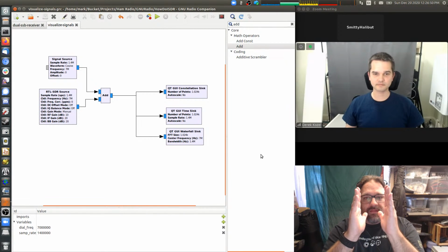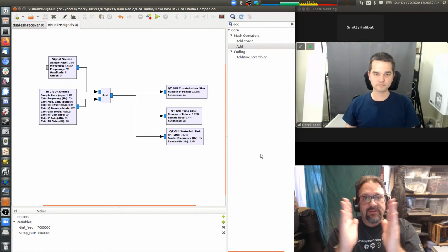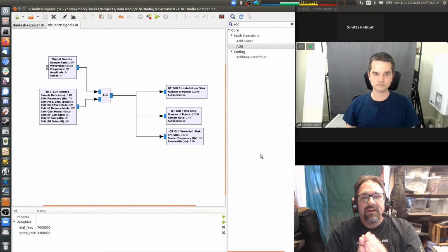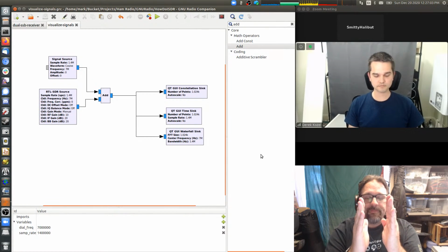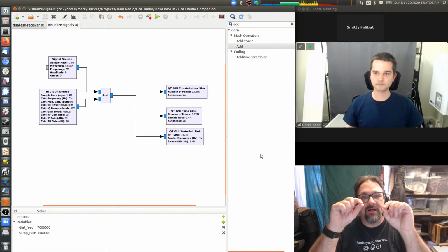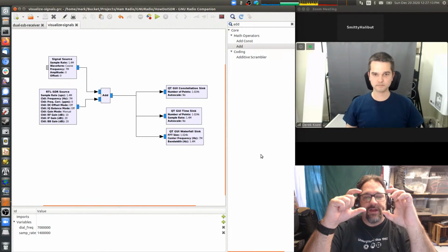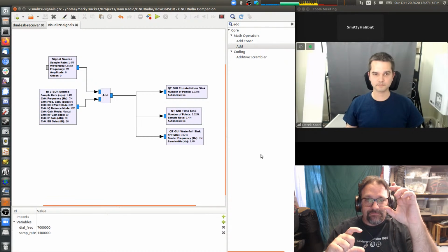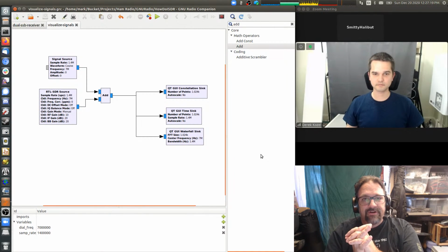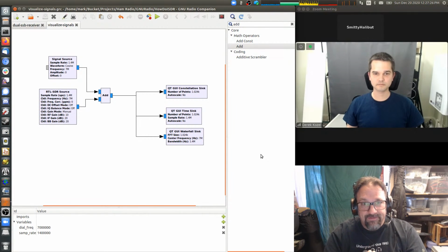And you can generate any waveform, any amplitude, and any phase by just summing a cosine and a sine wave of different amplitudes. Especially if you include negative amplitudes as well. But if you have an amplitude of a sine wave and an amplitude of a cosine wave between 1 and -1, and then you add those 2 signals together, you can represent any amplitude of that sine wave and any phase of that sine wave, right?